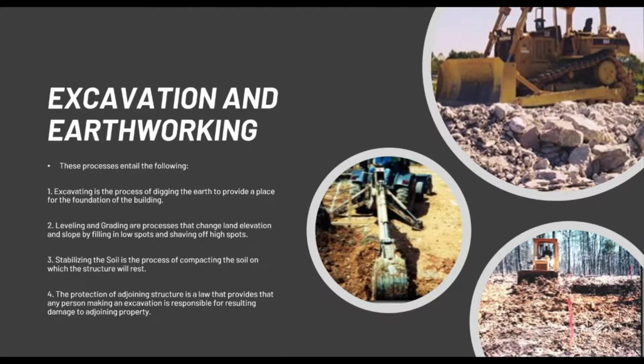Number three, stabilizing the soil is the process of compacting the soil on which the structure will rest. So, from the term itself, stabilizing the soil. And then number four, we have the protection of adjoining structure, a law that provides that any person making an excavation is responsible for resulting damage to adjoining property.